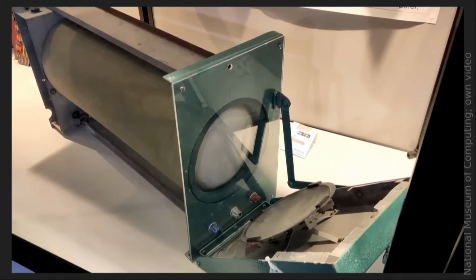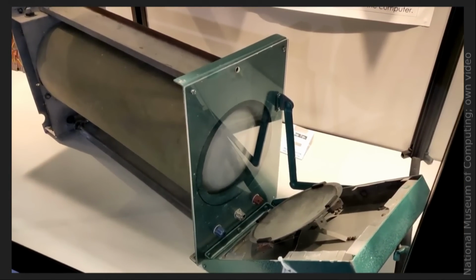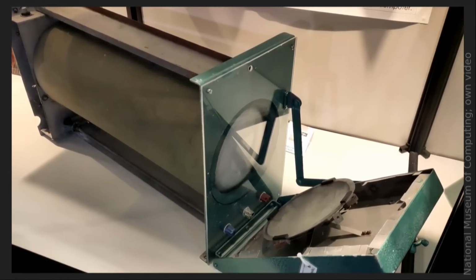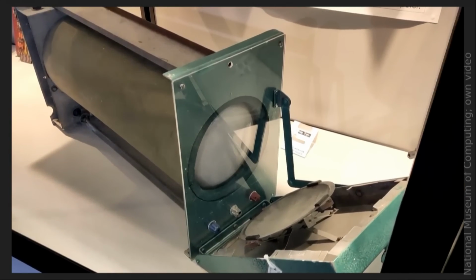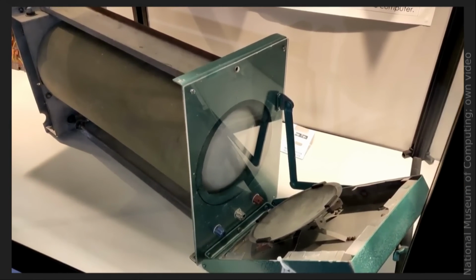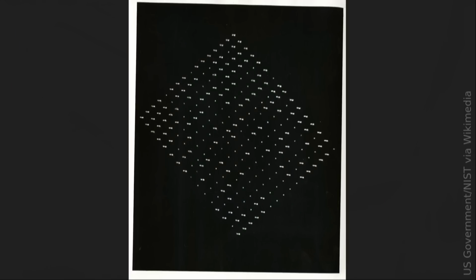Here's what one of these tubes looked like at the National Museum of Computing. Now, I'd long thought that the storage tubes had a similar construction to the DVSTs that we've been looking at, but no, they don't have flood guns, and they have to be refreshed like regular CRTs do. The patterns of the bits on the screen would look something like this, and it's read in a manner that makes use of secondary electrons in a way that you might be able to think about now. So check it out later maybe, and sorry for the tangent. It's my fault for getting confused by how the term storage tube is overloaded. One of them stores images, the other is part of a bigger mechanism that stores data using a more ordinary CRT.